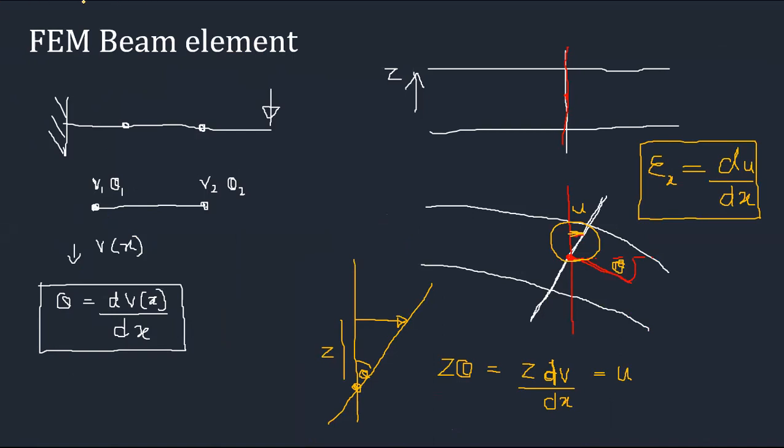So you have 2 degrees of freedom, and it does not mean that you have a third degree of freedom. That in the axial direction is restrained, because you usually don't have axial loading in the beam, so that occurs in the frame element, right? So in the beam element you have transverse loading usually, right? But if you want, you can consider it as a frame element and solve this method, right? So then the stiffness matrix will be different.